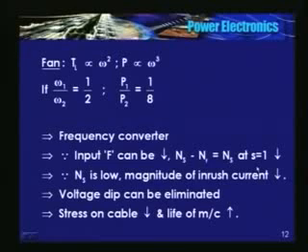So ns minus nr is nothing but s ns, where s is slip, and at starting slip is equal to 1. So ns minus nr is equal to ns itself during starting. Now if I reduce the frequency, ns has come down.